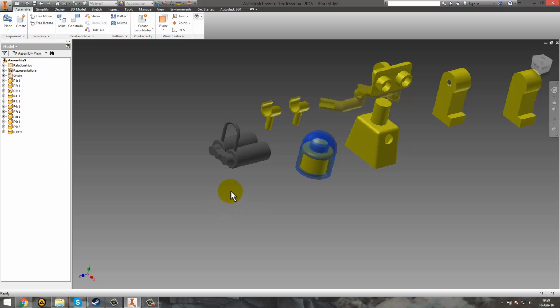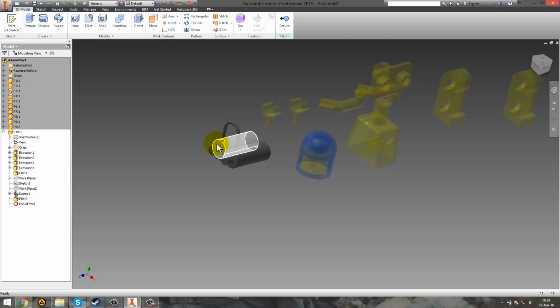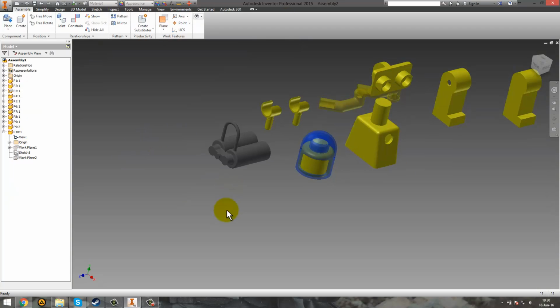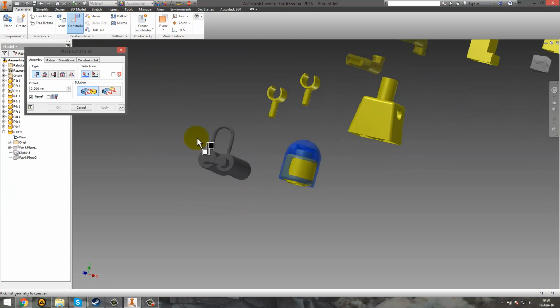When I did a rehearsal before this one, I noticed something bad, but I wanted to leave it like that in order for you guys to see how to repair something if it's bad. If you double click on the part, you can edit the part without changing the entire assembly. So the thing that I noticed, let me show you really fast.